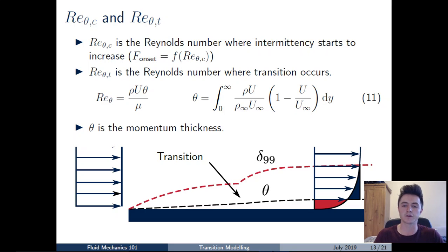If we think of boundary layer development from the leading edge of a flat plate or aerofoil, a conventional way we might measure the distance along the boundary layer might be a distance x, and we might divide that by the length of the plate or the length of the aerofoil, for example. That will give us a fractional distance along the length of our geometry. Now, for a CFD code, we can't really use that approach because our geometry could be very general and we may not necessarily have a flat plate or an aerofoil. We may have a more complex geometry.